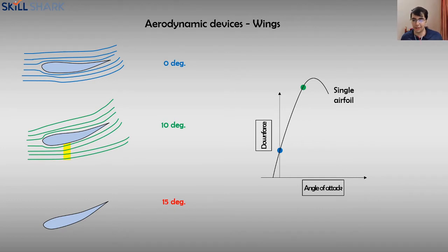So you have ambient airflow over here, and then you have the airflow that goes on the surface of these airfoils. And you see this point where flow starts separating away. Basically, the adhesive forces hold these fluids to the surface, and then you have the high energy flow here that rips the flow off that surface. And that's where Reynolds number comes into play, and it kind of tells you how aggressive or how turbulent that flow is. So there's only a certain angle up to which you can actually sustain this flow, after which the flow starts separating.